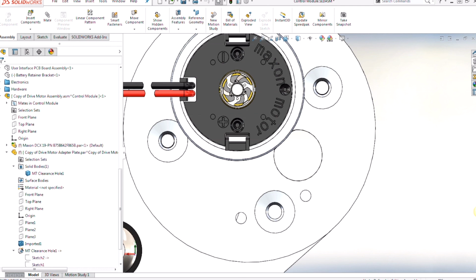In addition, we saw that the imported CAD data can be updated with newer version files, allowing us to preserve mates we made beforehand. And lastly, we discovered that if we needed to break the associative link, we can do our own editing with feature recognition instead of having to wait for the vendor to provide us with the correct model.